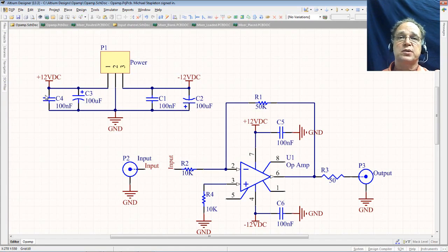This ceramic capacitor is made with a little ceramic disc. If you made a big one, it would look like a coin made out of ceramic, a little flat disc. They plate metal on both sides of the disc, and then they hook leads to those plates. That gives you a small surface area, where the electrolytic gives you a large surface area, but this little capacitor has a very low ESR. It can dump its current very quickly. It can't hold a lot, but it can dump it quickly.